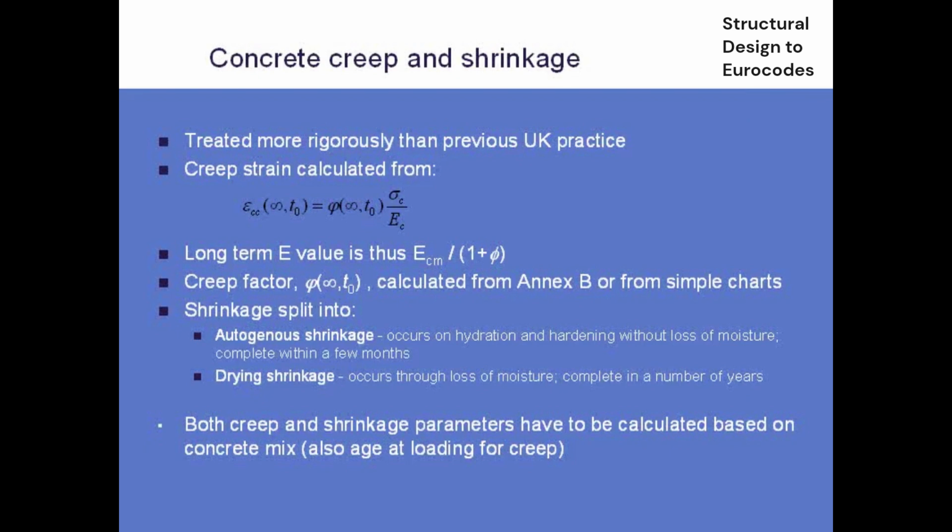In terms of creep and shrinkage, we'll see a lot more of this tomorrow when we do pre-stressing. But it's unfortunately treated in a much more rigorous way than it was in BS500. So unfortunately, gone are the days where we can just say, well, here's the short-term E value, and the long-term modulus for dead load is just half of that. Well, you could do that, but you're just making up a number.